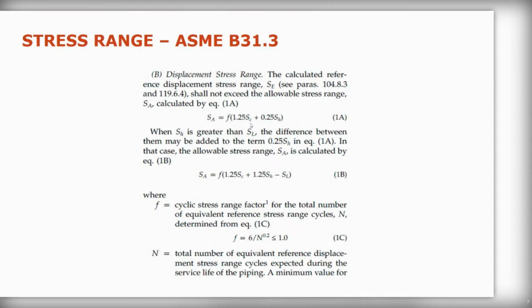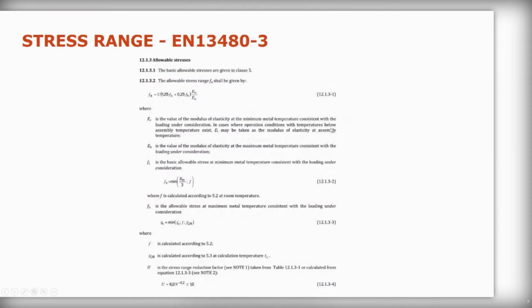Now, there's a little bit of theory there about shakedown and ratcheting. I don't have time to go into it, but I just need you to understand that that is there. And if you want to understand better, you can look it up in a bit more detail. But just understand that the requirements for maximum allowable stress for secondary stresses, such as thermal expansion, are different. Therefore, they have to be considered separately.